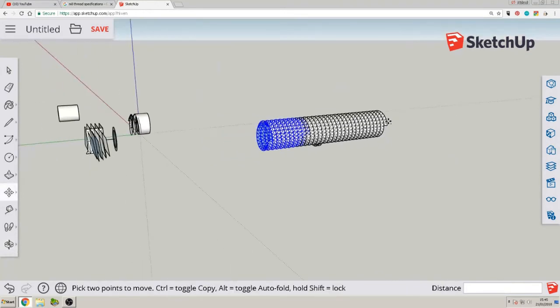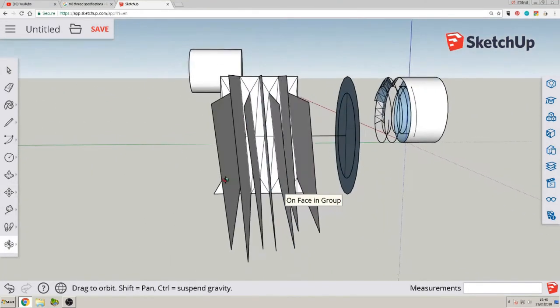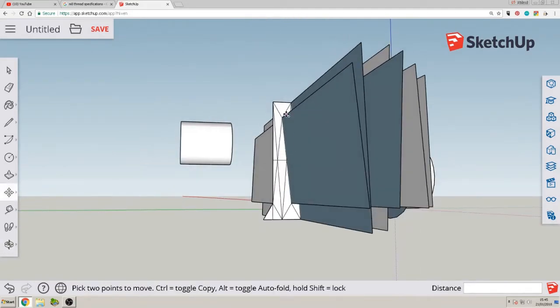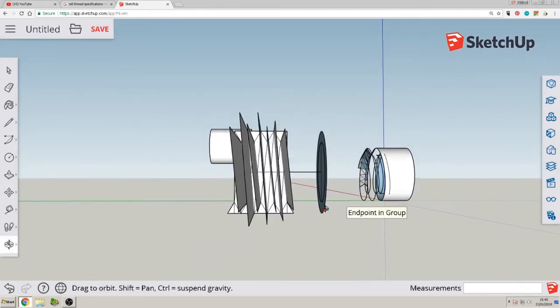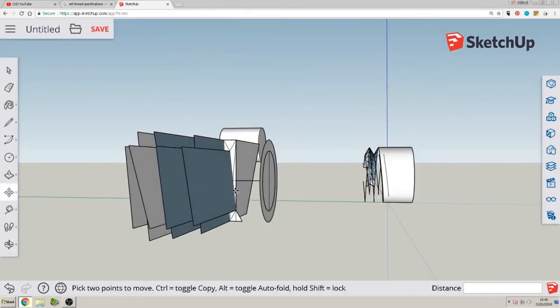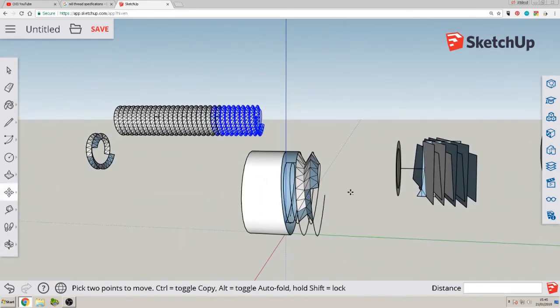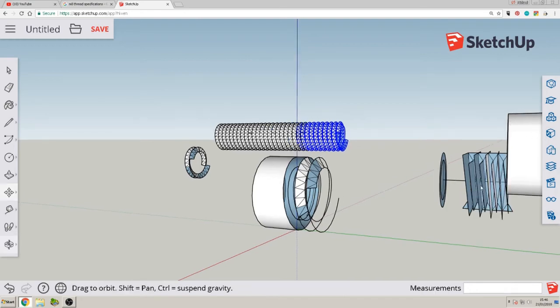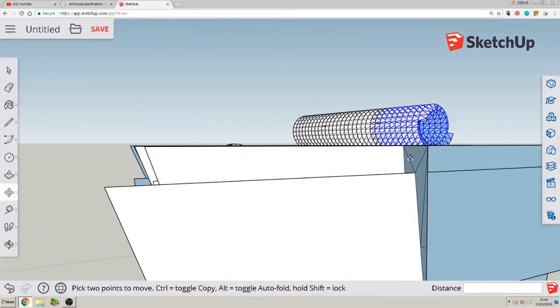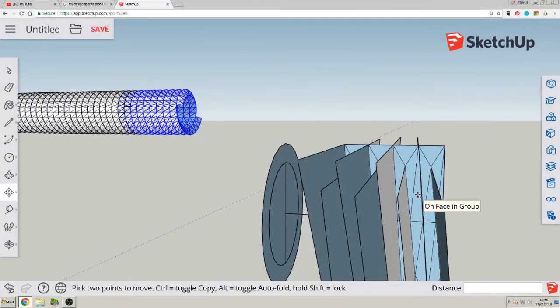So, just to recap, remember, you've got to make the profile of the thread and then flip it round and do one way on one side with the cutting plates. I'm going to call these the cutting plates of our cookie cutter, and then the opposite direction on the other side, but make sure that they start at the same peaks and the same troughs on each side, and use an equilateral triangle, because you know it's 60 degrees on this thread, so 60 degrees is an equilateral triangle. If you're using any other sort of thread, you'll have to find out the angles and stuff before you start.